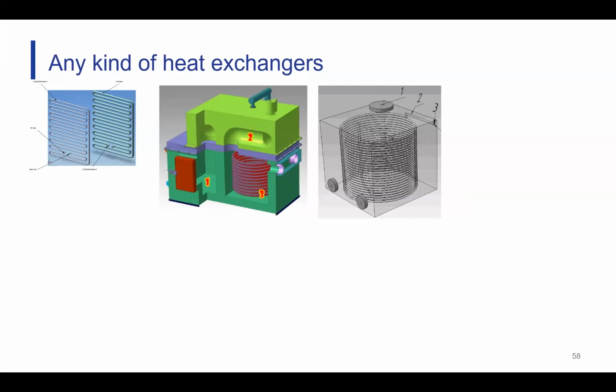As the core and the windings heat up, the temperature in the tank rises. This is going to be heating the oil, and it's going to cause the oil to move upwards to the upper portion of the tank. There it begins to dissipate the heat, being cooled by air out to its surroundings. And as it does that, it cools down, begins to flow back down, and re-enters at the bottom of the tank. So far, so good. Basic heat transfer problem. We've seen a bunch of these in this presentation.